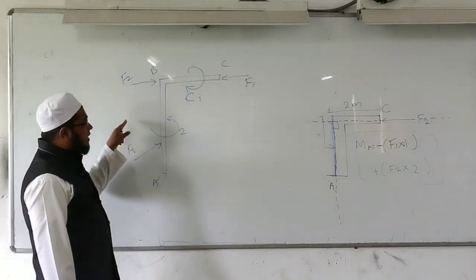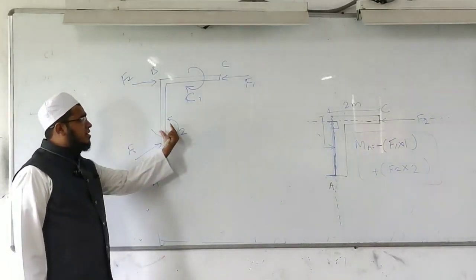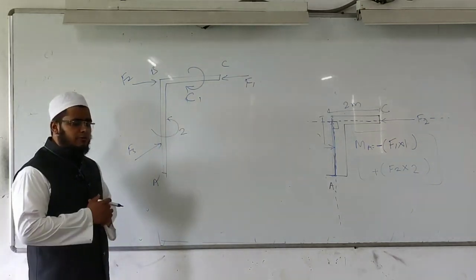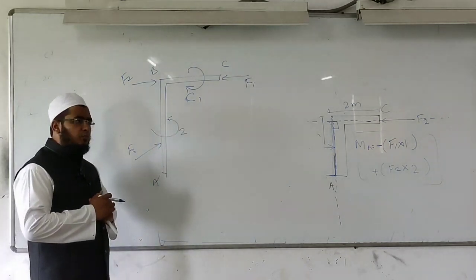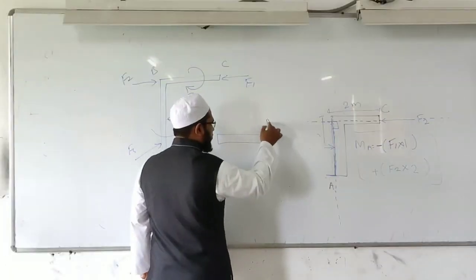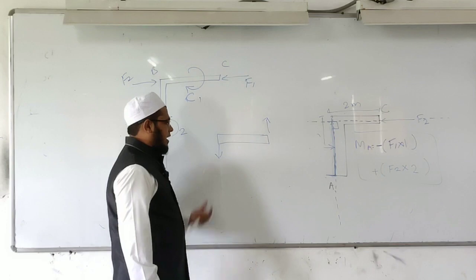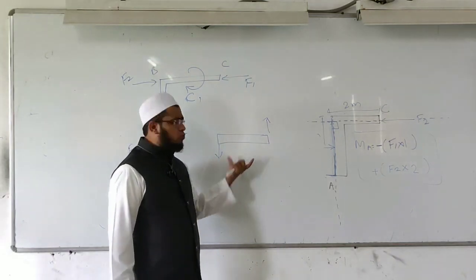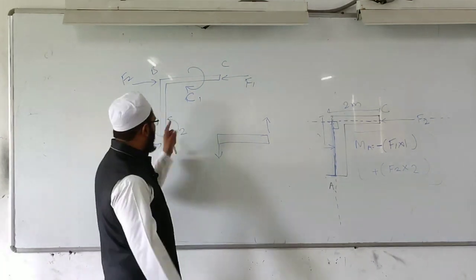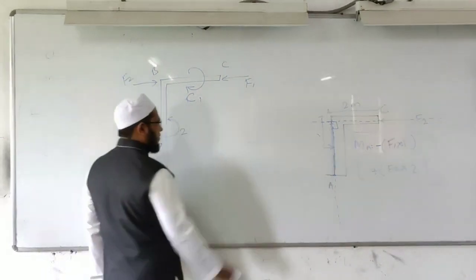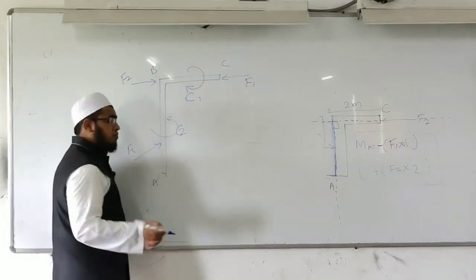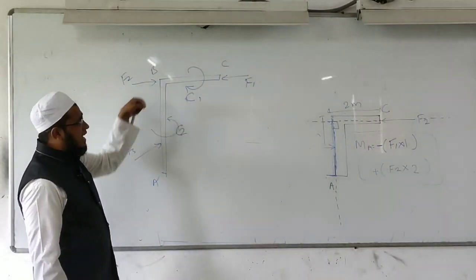When I calculate the resultant, in the resultant I will not consider the couple. Why are we not considering it in the resultant R? Because a couple has two unlike parallel forces of equal magnitude, and both cancel the linear effect. That's why we will not consider it in the resultant. But in moment we will consider it as it is.